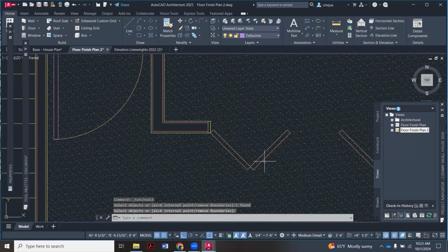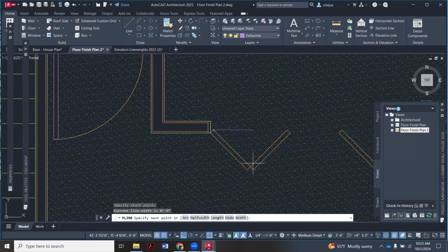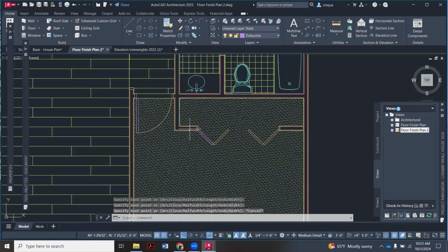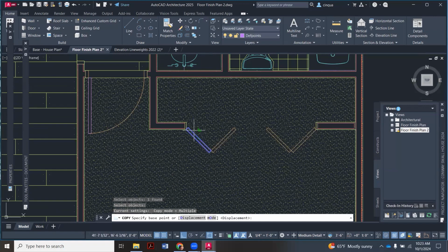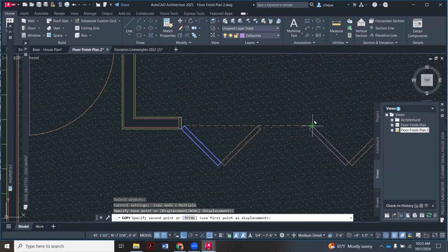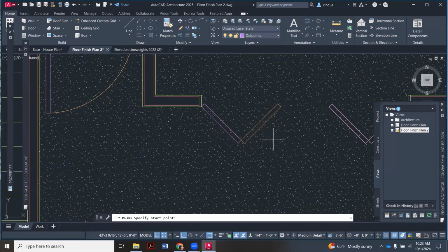Now here on these bifold doors, unfortunately, what you're going to have to do is get a polyline and do it individual panel by individual panel, because the way the angles work does make things a little wonky for CAD. Once I've drawn this first door, I'm going to copy, paste it over here, and do the same for the other side. So let me do that quick so you can see what that looks like. Again, I'm just tracing over this door here.